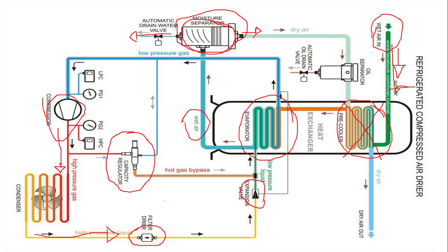The temperature and pressure of the condenser on cold days, and the liquid line, work very low, and this is not good because it can return liquid in the suction and break the compressor. Because of this we use the condenser pressure regulator.